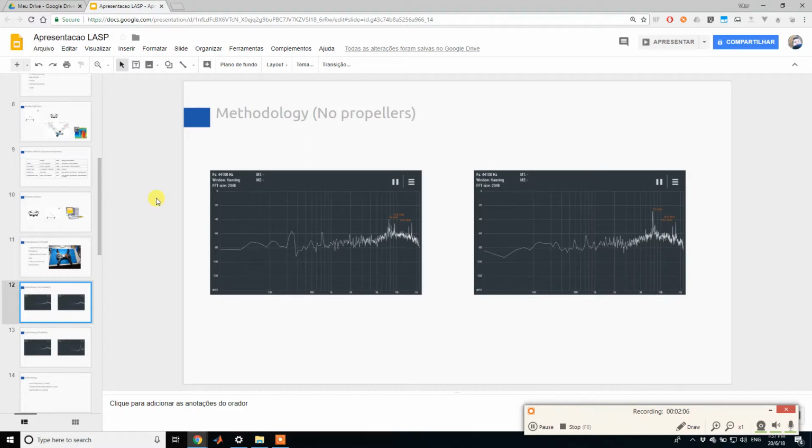to determine the frequency. First, we use the drone without propellers, just to test what frequencies they are emitting sounds. And with no propellers, it's a lot of noise, but they start at low velocity of the motors. You have this case when you have a lot of frequency concentrated around 7.6, but when you spin the motors a little faster, you can start to see components on the average frequency between 16 and 17 kilohertz.